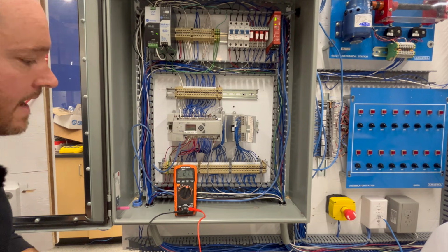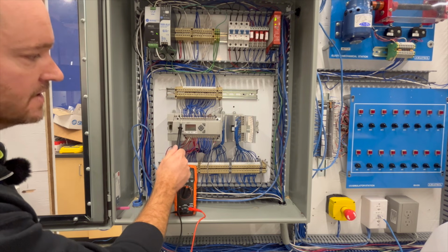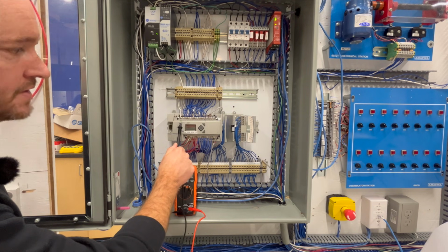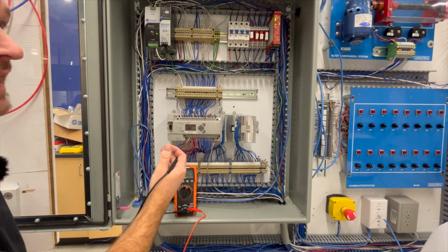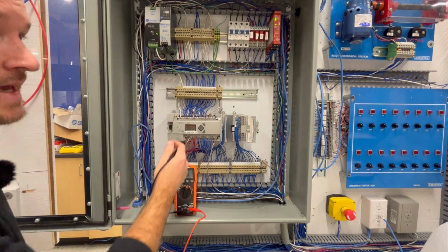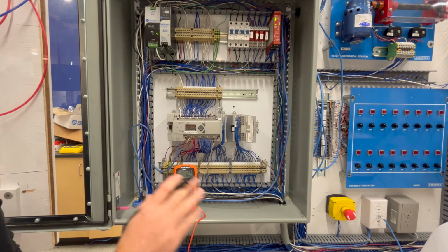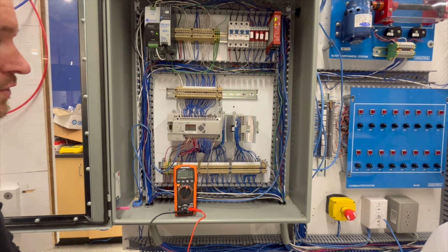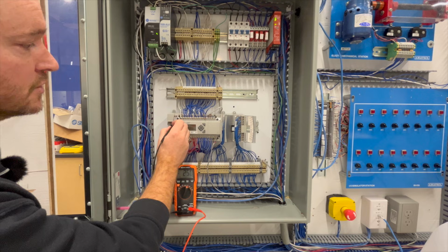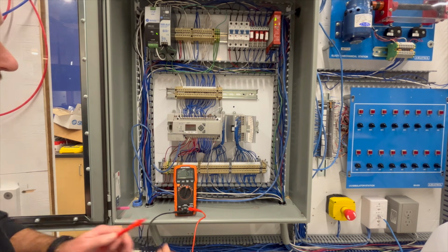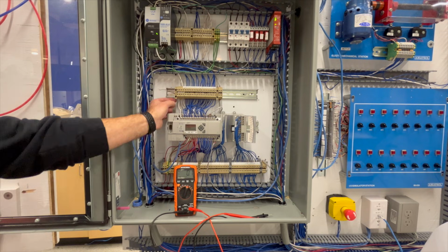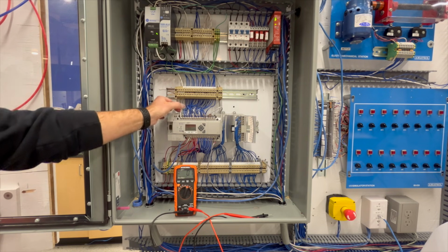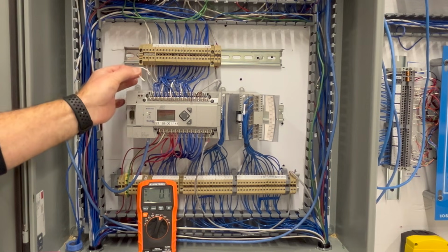So why this is very important is if I was getting 24 volts here, the traces on the circuit board behind here might have gotten burnt out. And if that was the case, that would send us down a whole other area of troubleshooting. But I'm not getting 24 volts here. So I'm looking now at this point probably for a loose wire or something like that that would exist between here and here. And look at that.